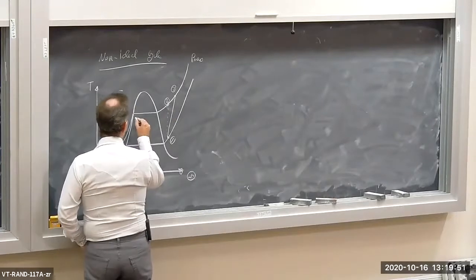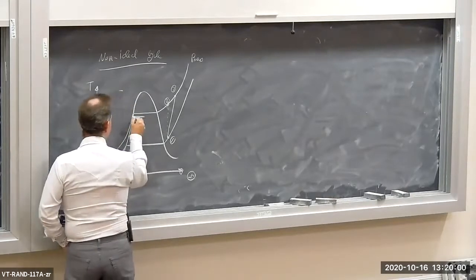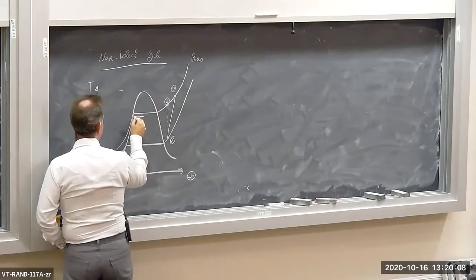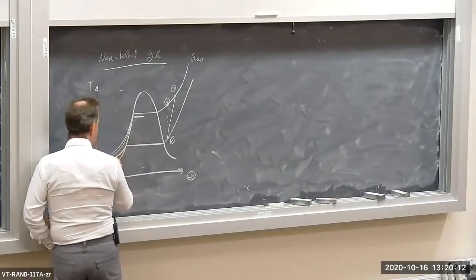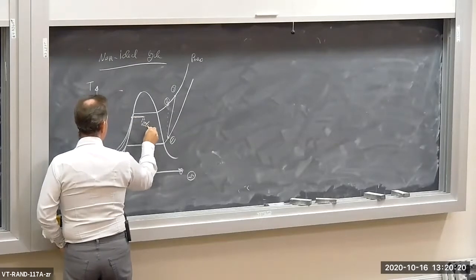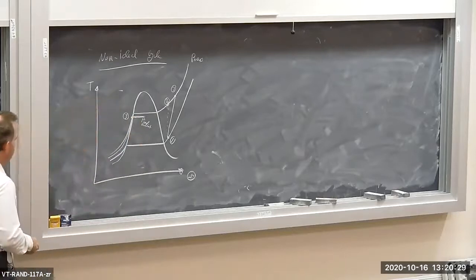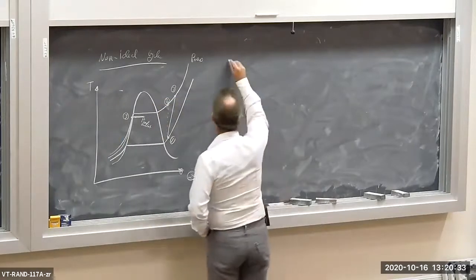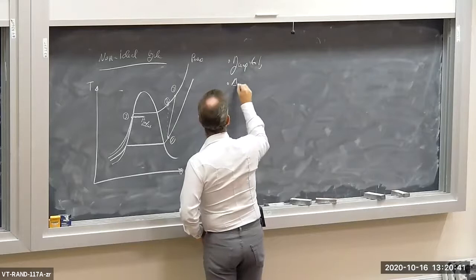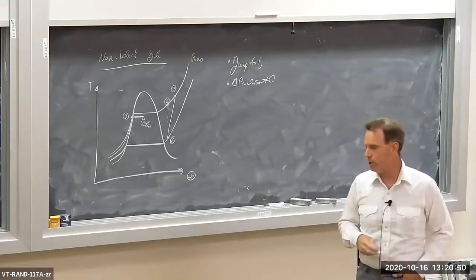We could have a pressure drop in the what? In the condenser. So the condenser is like a radiator, it's a heat exchanger where the fluid is turning from a superheated vapor into some kind of a liquid. So we could end up at some lower pressure. So we could have P condenser outlet. We could have a pressure drop in the condenser due to friction. And so state 3 might look something like this. So we could have isentropic efficiencies of the compressor less than 1. We could have a delta P across the condenser. So this could not be equal to 0. We could have a pressure drop across the condenser due to friction.